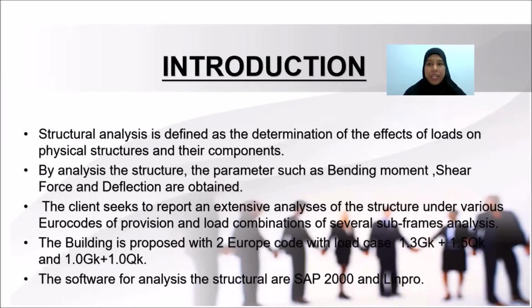Also, in this project, the task was given by the client, who asks for a report and extensive analysis of the structure under various Eurocode provisions and load combinations of several subframes. The building is proposed with 2 Eurocode load cases: 1.35 GK plus 1.5 QK and 1 GK plus 1 QK.